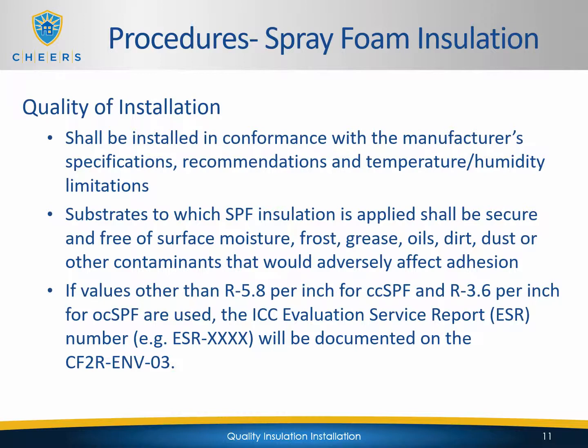In addition, SPF shall be installed in conformance with the manufacturer's specifications, recommendations, and temperature humidity limitations. Substrates to which SPF insulation is applied shall be secure and free of surface moisture, frost, grease, oils, dirt, dust, or other contaminants that would adversely affect adhesion. Also, if values other than R5.8 per inch for closed cell and R3.6 per inch for open cell are used, the ICC Evaluation Service Report Number, ESR, will be documented on the CF2R EMV03.